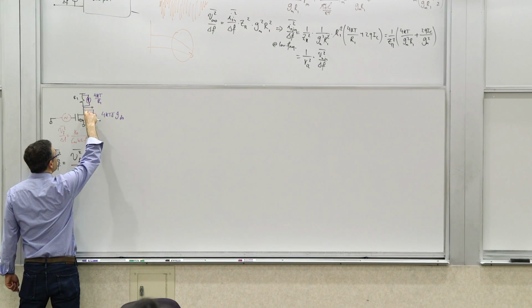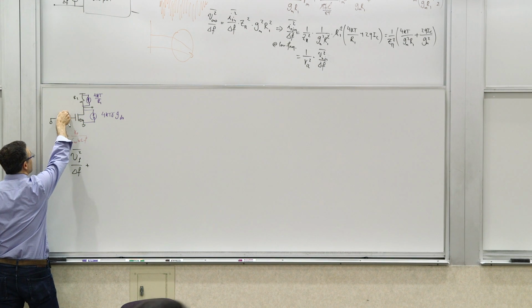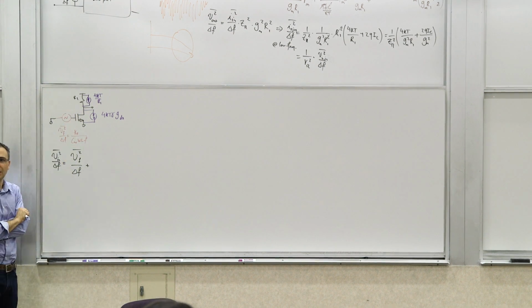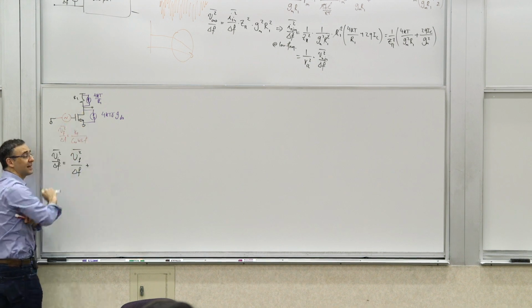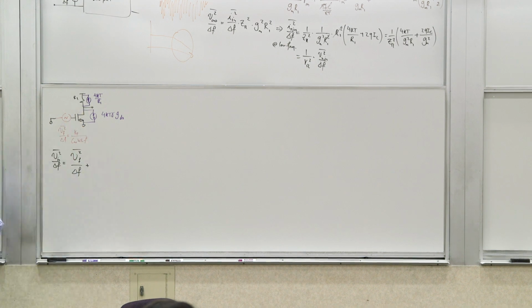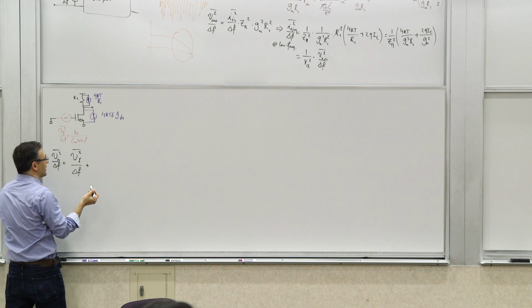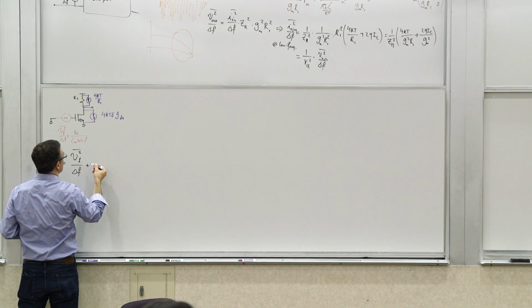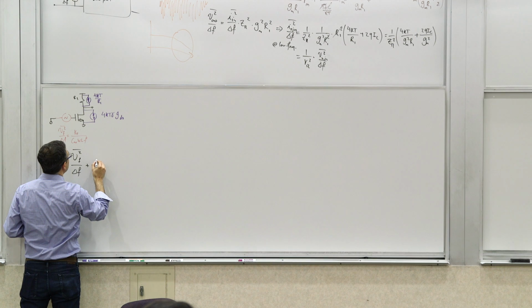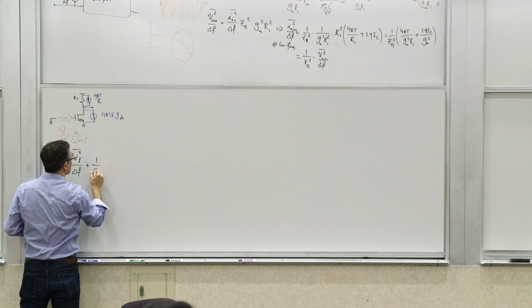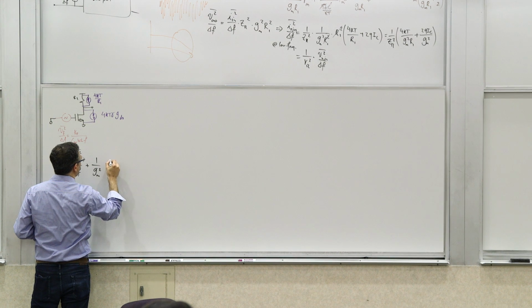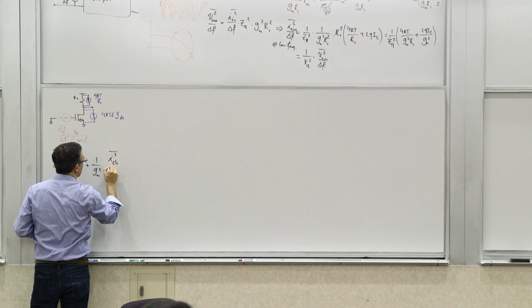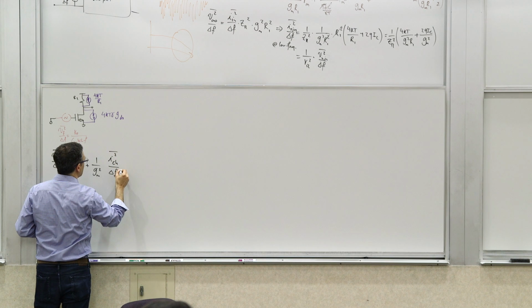Now, how does this noise current source at the output translate to a voltage source at the input? What is the transfer function from a voltage here to a current there? GM, right? GM's magnitude, GM squared really, at low frequencies if you think about it. So you have to divide it by GM squared. So you get basically 1 over GM squared times whatever that channel noise is. So we can call it I channel squared divided by delta F, which is this quantity.